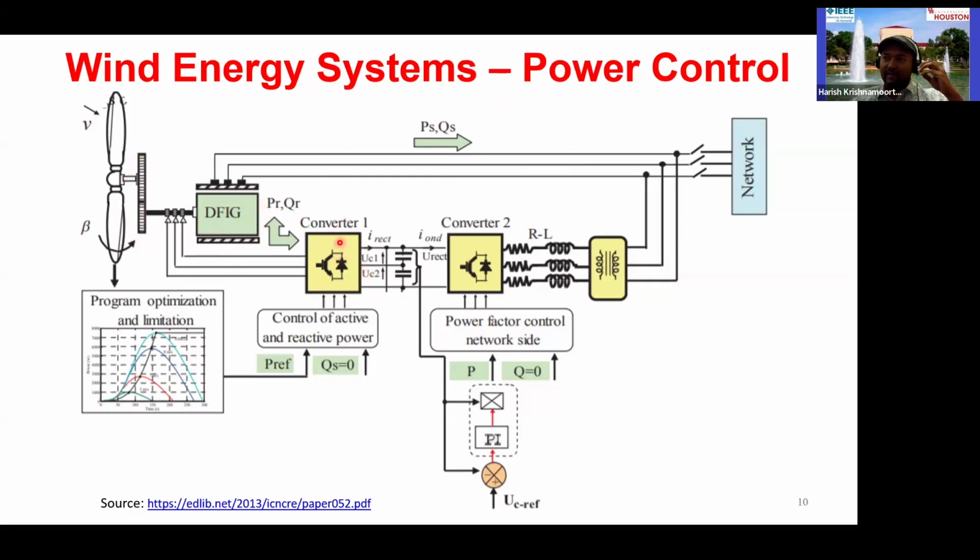that will have these power converters directly on the lines. So you will need a rectifier that transforms the variable frequency AC to a DC, and from the DC, generally there is another converter, which is an inverter, that takes it to the grid frequency. Sometimes you may be able to take this DC after the rectifier and take that to a collection point, let's say if you're interfacing with multiple wind turbines at the same time. So this is something to remember.